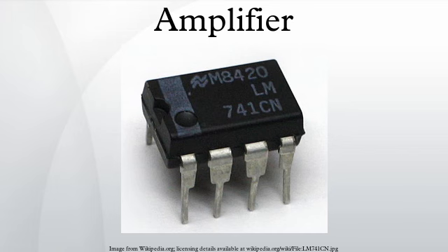Negative loop feedback has the intended effect of electrically damping loudspeaker motion, thereby damping the mechanical dynamic performance of the loudspeaker. When assessing rated amplifier power output, it is useful to consider the load to be applied, the form of signal, that is speech or music, duration of power output needed, for example short time or continuous, and dynamic range required, for example recorded program or live.